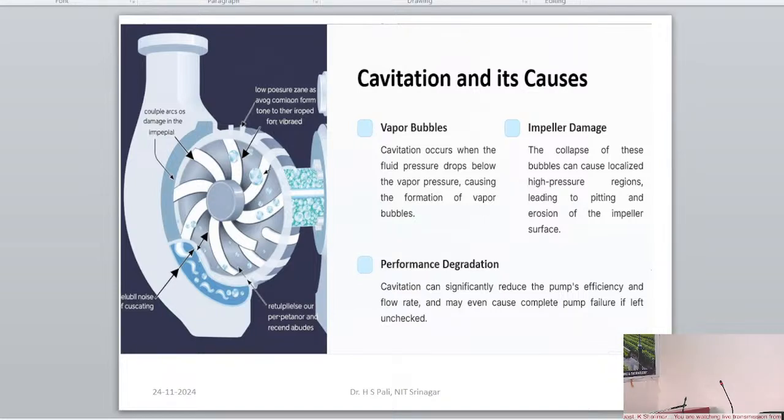But with the same pump, if you opt for this other option, where the flow is in between, 125 to 140, then in that case the discharge head is 30 meters, and the efficiency is 73%. So optimizing these parameters plays an important role. If you utilize your system effectively, that is one of the points we can understand here. So this is the purpose of showing these pumps.